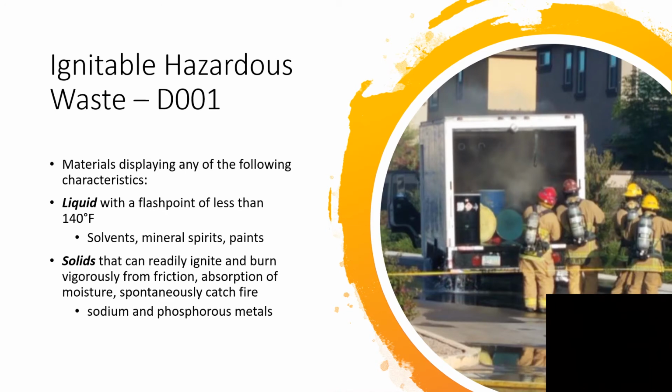First is ignitable waste. This can be any material displaying the following characteristics: a liquid with a flash point of less than 140 degrees Fahrenheit. This can include solvents, mineral spirits, as well as paints. Also, solids that can readily ignite and burn vigorously from friction, absorption of moisture, or even spontaneously catch fire.